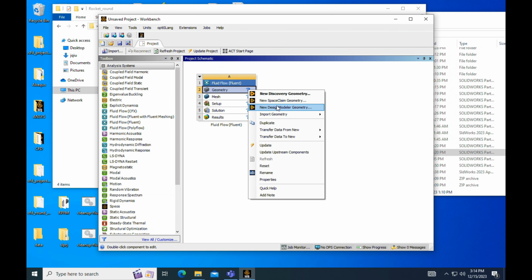We're going to insert our method for how we divide up the elements within our mesh. And we're going to make sure that the body selection tool is on, and we want quadrilateral dominant method. Now we begin inserting sizing for each of our meshes. The closer it is to the rocket body, the higher resolution we want the mesh to be. And so we're going to change also metric down there from meters to millimeters because that's the size we're working on. Saves on computational power.